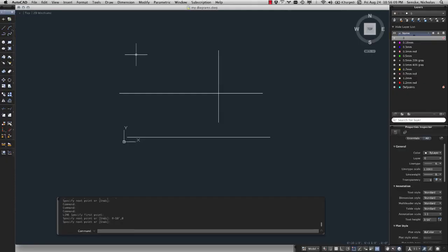And the at symbol, you might have a question about that. The at symbol means that it's in relation to where you start the line. There are actually coordinates. If you look on the bottom of the screen, it tells you exactly where the mouse cursor is. And 0, 0 is where this little world widget is, this XY coordinate. But I don't know about you, but I find it really hard to know exactly where I am on the screen and know exactly where the exact point's going to be.